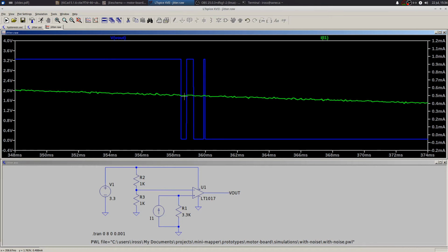So it goes below the threshold, then it goes above the threshold, below again, before it finally settles down to staying below the threshold. And this is a common thing with looking at any slow-moving or smooth signal with a comparator. You're always going to get this kind of spurious switching if you're not careful.